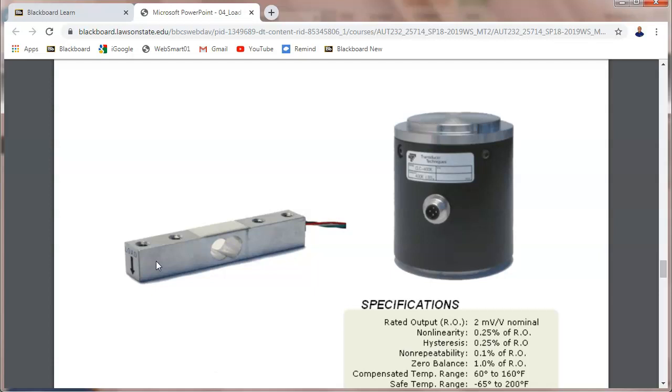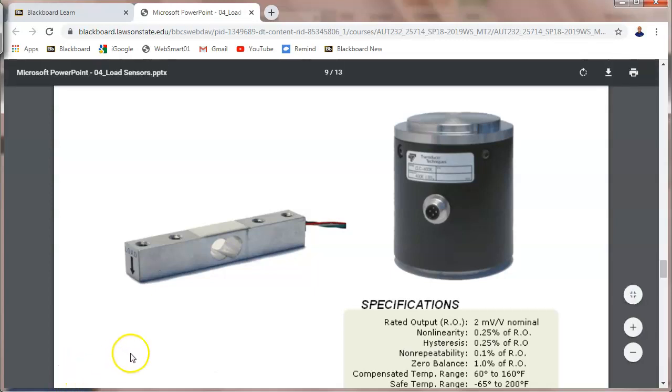You know, on truck scales, we'd put the 50,000 pounds on the one end, and we'd put them on the center, then we'd put them on the other end. And then you calibrate what we call the span. You calibrate the span on the scale. Because what would happen, and y'all might run into this, is that first of all, you would set a 0, right?